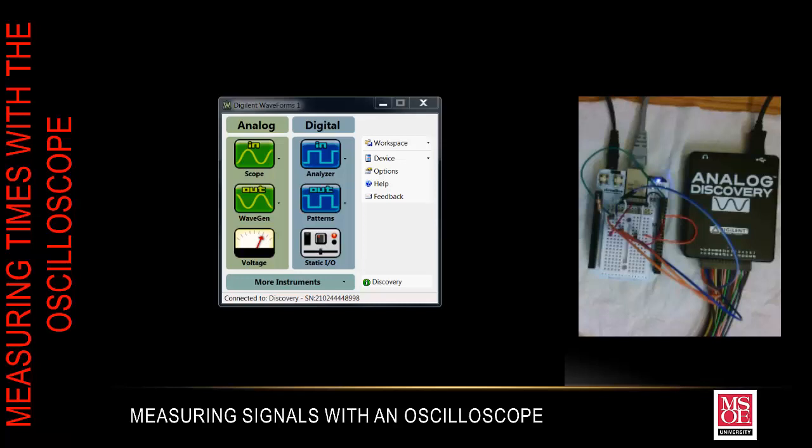So at this point, I've started the Analog Discovery Digilent Waveform software, and I have this window that's showing in front of me right now. What I'm going to do is start my LED toggling, so we can see that on the screen now where it is blinking at a 500 millisecond rate, so on and off once per second. And what I want to do is start my oscilloscope up. So the oscilloscope is opening, and we'll see it momentarily here as it comes online.